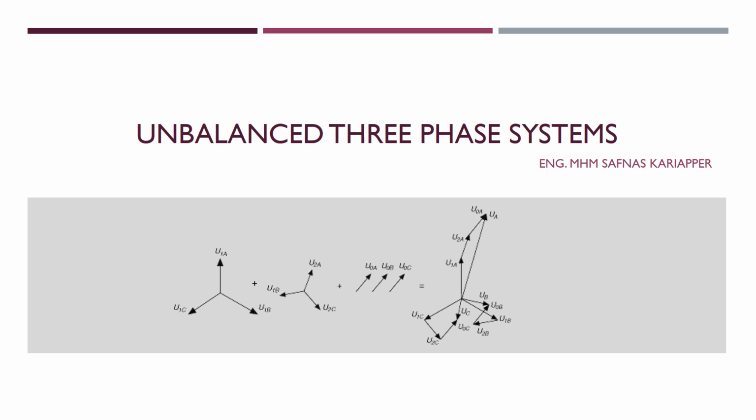If it is an unbalanced system, UA cannot be equal to UB as well as UC, and the phasor angle between them cannot be equal to 120 degrees. In that concept, these unbalanced phases can be split into three different balanced systems. We will see that, it is the theme of our discussion. So this is a kind of introduction before beginning the lecture. Anyways, we will move on.